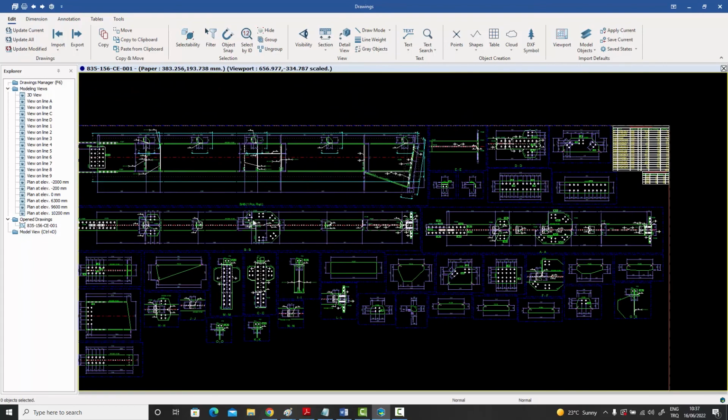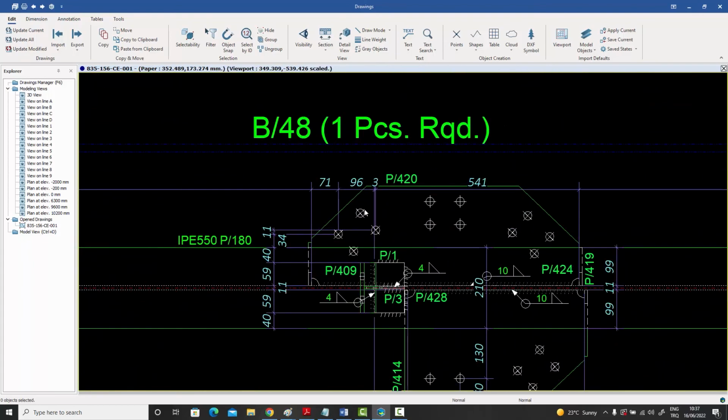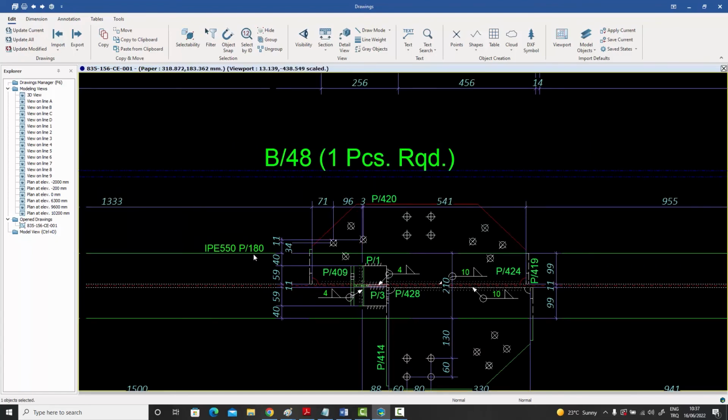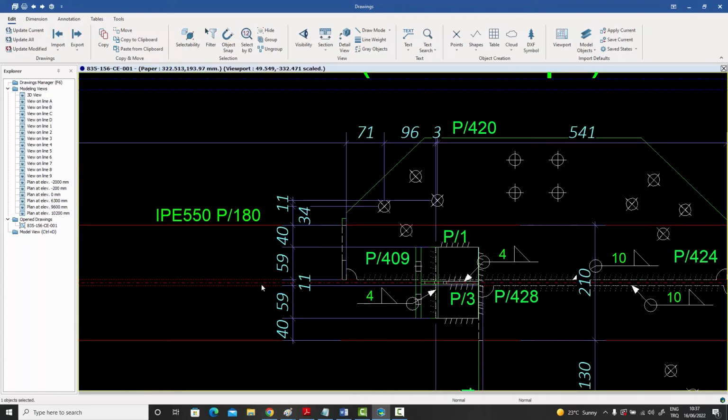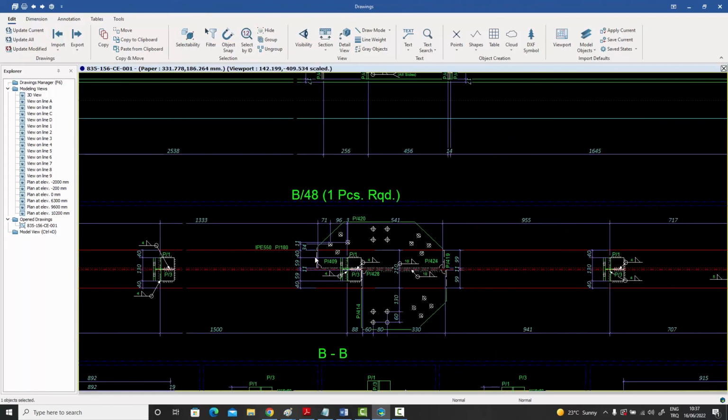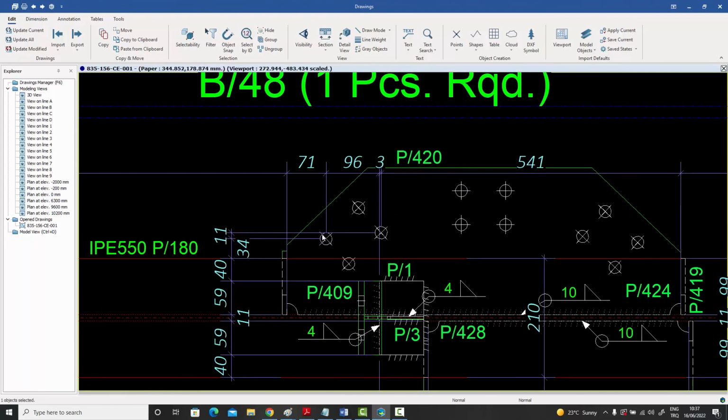And then we had talked about a setting for how the parts on the assembly will be dimensioned. So if you notice over here, it has dimensioned according to both the edge of the part, as well as the bolt over here. So we can modify whether we want this. We talked about certain tolerances, that this plate might be cut at a bad tolerance, or this rolled profile might have a web thickness which is slightly smaller, or the length might be cut a bit. So if you dimension your part by bolts, it's usually a better practice.